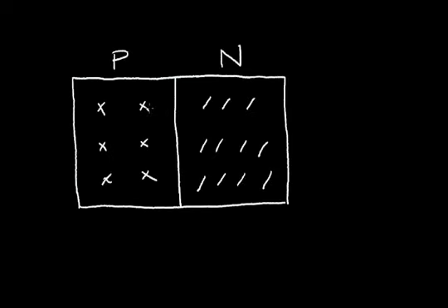Now we said that some of the holes would diffuse to the right and the electrons would diffuse to the left. And when that happened, we set up an E field at the junction. And this E field opposes further diffusion of carriers. So we said that we developed in the junction a depletion region.